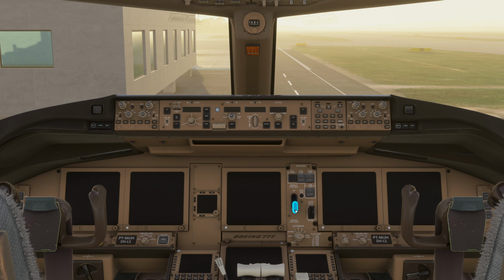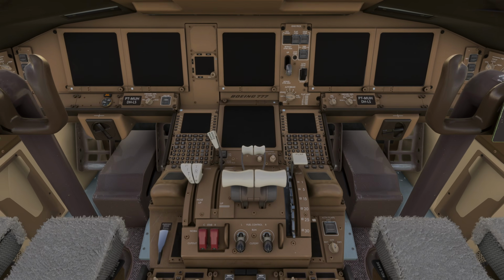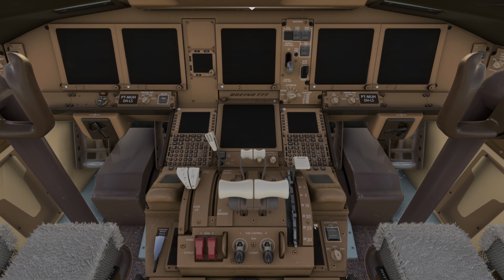The last step before applying electrical power is to check that the alternate flap selector is in the off position. This is the alternate flap selector. You have 3 options here: retract, off, and extend. So you want to make sure this is in the off position, so then it doesn't matter what you are doing with the alternate flap master switch. If you keep it in off, the flaps are not going to electrically move, extending or retracting.